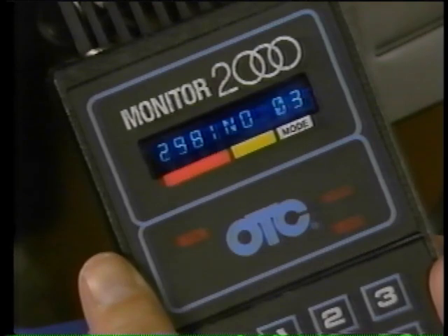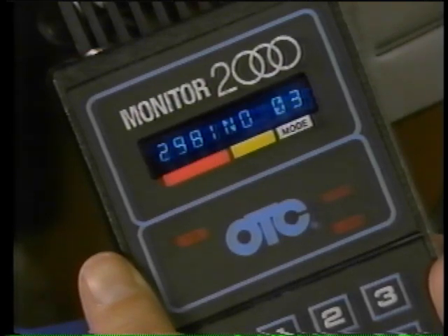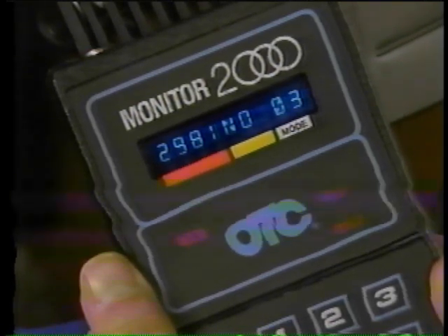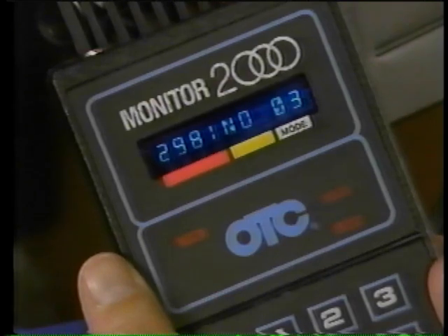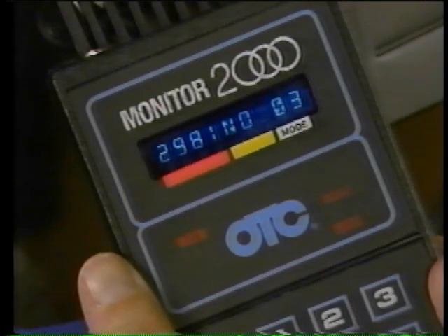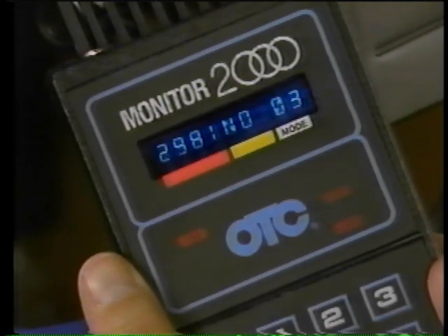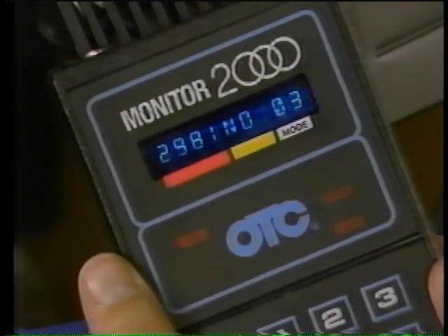The display will show 3 sets of numbers: PROM ID, stored trouble codes, and mode selected. Each set of numbers will appear directly above the 3 color-coded bars. And keep in mind that the display will change according to the mode you select. If no trouble codes are stored, the word No will appear. If this happens, test the vehicle following the drivability symptom section in the shop manual. However, in this case, 2 trouble codes appear on the display, a code 13 and a code 63.